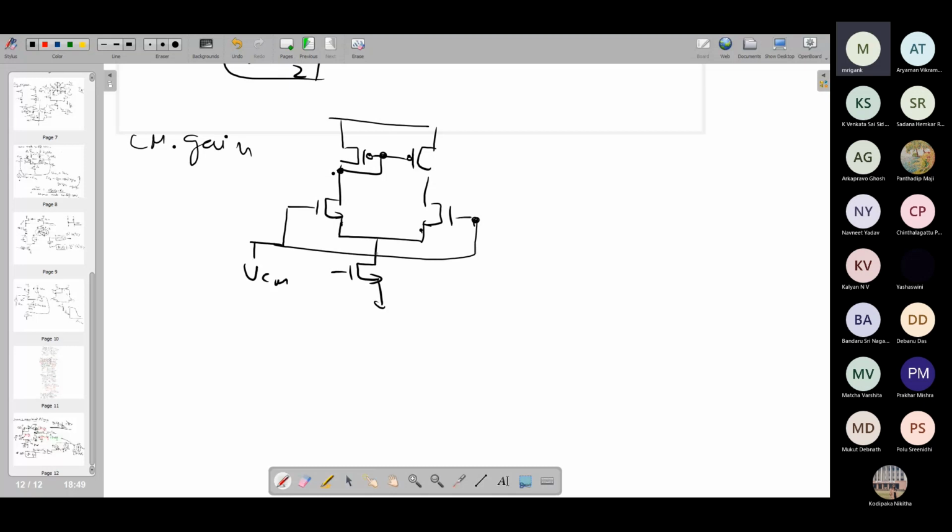So again, remember that when I am crossing two wires vertically, like this vertical wire is crossing this horizontal wire, there is no dot. If there is no dot, that means they are not connected. So when there is a wire like this, if I don't have a dot here, it is not connected. Only when there is a dot, they are connected. If it is just like this, then it is assumed it is connected. But still, for clarity, I will make a dot here also. Like here, I have done it just to make it clear. Here also, let us keep the dots just to keep this convention uniform.